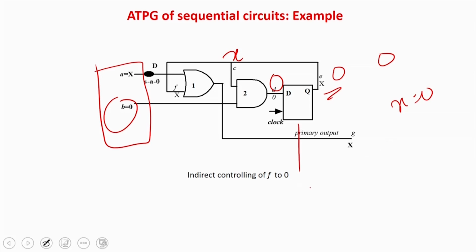Basically you can directly make the reset line equal to 1, so that directly it will become 0 and you can do the job. And the advantage here will be, if even there are 200, 300 flip flops, all the set and reset lines will be controlled separately and they can be brought to their required values. So you require just one clock period, or you just require one test pattern to set and reset all the flip flops as required by the test pattern.